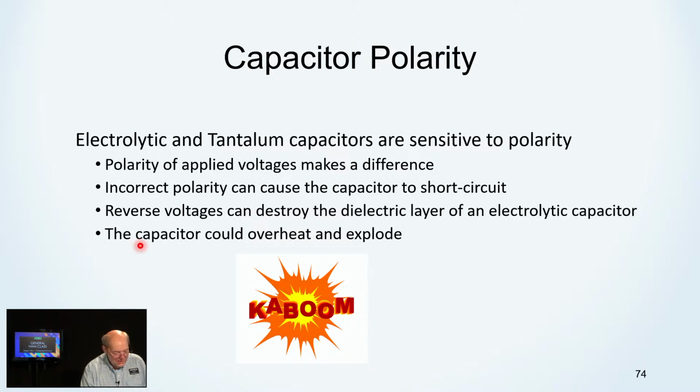So polarity applied makes a difference. Incorrect polarity can cause it to short circuit or destroy the dielectric layer. Then it basically becomes a short circuit. It could overheat and explode, and it lets the smoke out in the most unpleasant way.